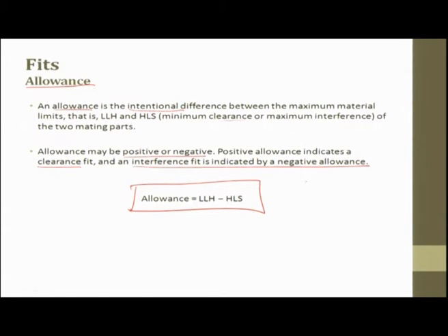What we do is we start giving the dimensions for the part. You are supposed to find out the tolerance, then the maximum material condition and the least material condition. Then from here you will have to find out which fit it is, and then find out the allowance, whether it is positive or negative, and solve. You can expect a problem of this type in the examination.